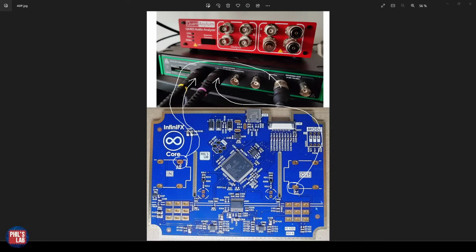I've hooked up our bottom DSP board to power, so 9 volts DC, as well as this serial wire debug connection to my computer for programming. I'll be using my Analog Discovery Pro, which is a USB-based oscilloscope and function generator, where I have 2 oscilloscope channels, one to monitor the input, one to monitor the output, as well as one of these wavegen channels to produce my input stimulus, so we can produce sine waves, square waves, and also do frequency response measurements later on.